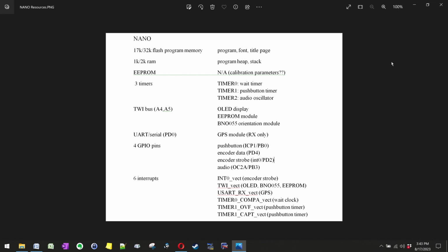There's no interrupt service associated with Timer 2. Timer 2 generates a pulse train of varying frequency to produce sound at the piezo speaker. The CPU turns on the timer and turns it off, and in between feeds a varying waveform to the timer on the fly. Other than that, the timer is free running. The CPU doesn't need to maintain the pulse train or have any interaction with the timer except to change the wave period. So there's no interrupt associated with Timer 2.